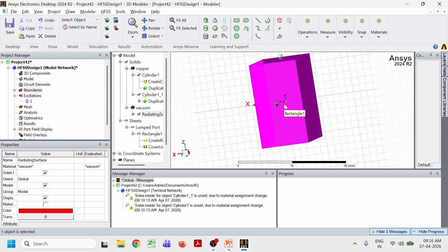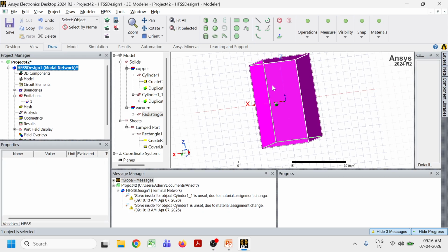So this antenna is going to be placed at a space where all other physical aspects are out of reach, right? So the simulation region is going to be considered like this for 15 gigahertz. If you have selected a much lower frequency, the dimension may be slightly larger, according to whatever frequency you have selected.